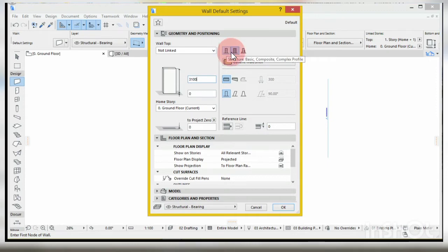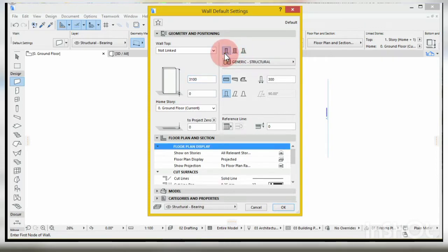So you can see this place here. So you can see how it is. I'll just choose this because I just want to use normal block wall. So this is just a kind of complex of it. So as I've chosen it, I will just come here, and this is the block wall, the width. So let's say I'm using 150. You can select 150, that is 6 inches. You can select 125, 5 inches block. You can select 225 block, depending on what I need. So let me just work with 150 block, which is 6 inches block. So I'll just leave it at 150.